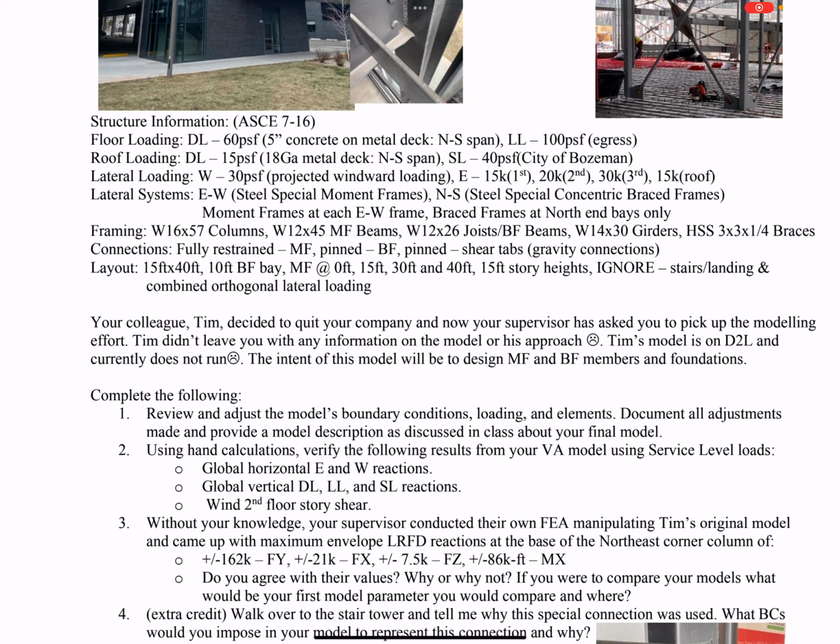We have 15-foot story heights. We want to ignore, okay, I did not model, and I don't expect you to assume that that's what I wanted you to model, is the stair landings, or look at combined orthogonal lateral loading, right? Don't worry about the fact that you need to look at wind in like 75% in one direction, 75% in the other direction, okay? Don't worry about that contribution.